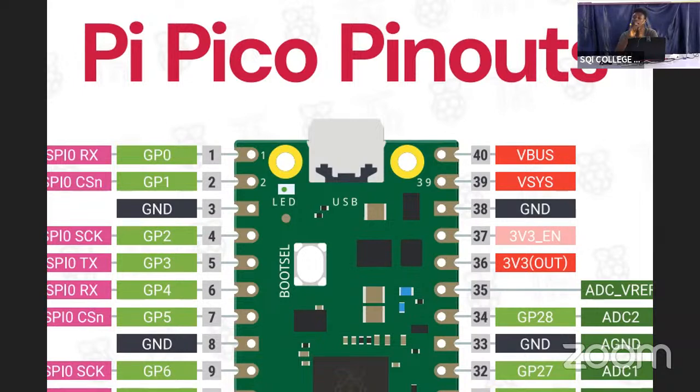That means I can get an analog input and convert that analog value to a digital value so that I can use the value to perform certain functions. Some of these pins are I2C, inter-integrated circuit, a type of communication protocol, more like your USB. And then we have some pins that perform SPI, serial peripheral interface. And then we have some pins that perform PWM, pulse width modulation. Later in this class, we'll be going through all these pins and we'll be seeing their functions.